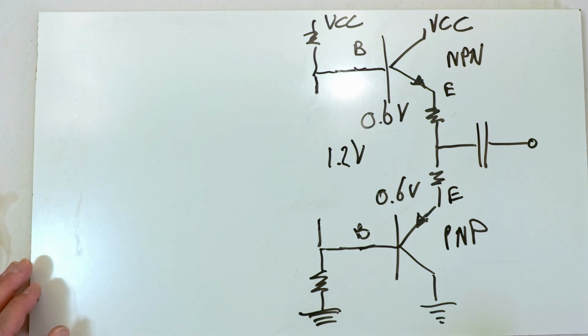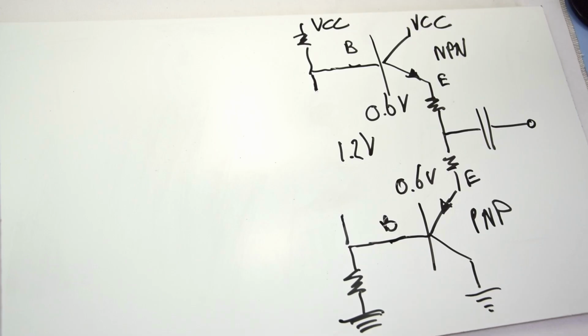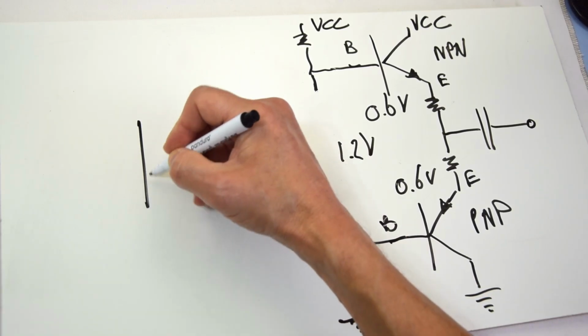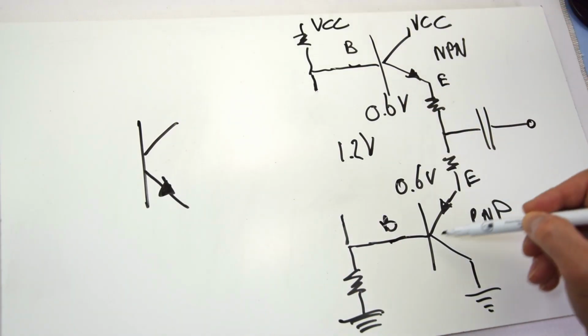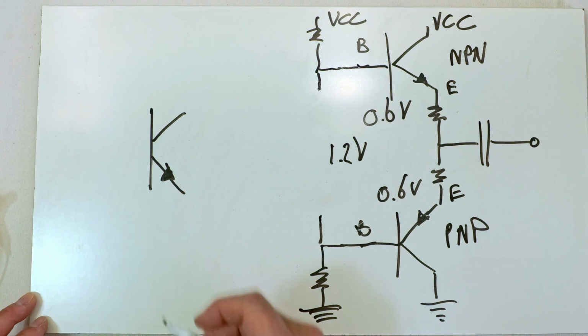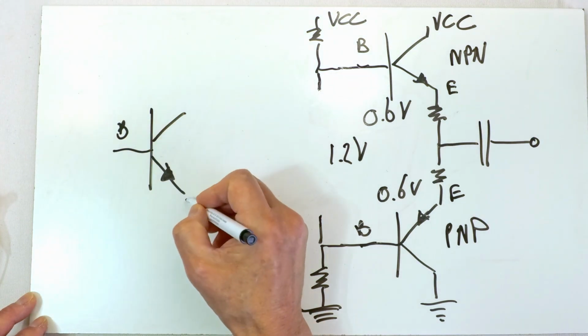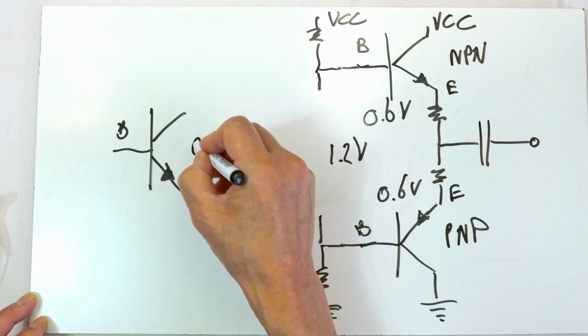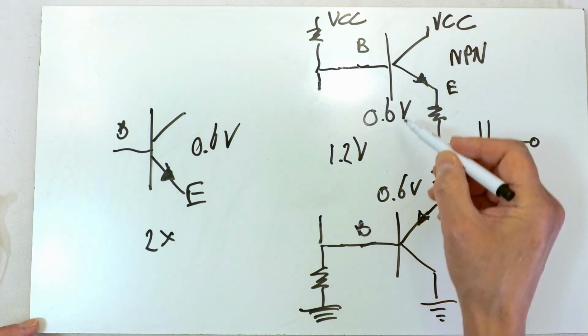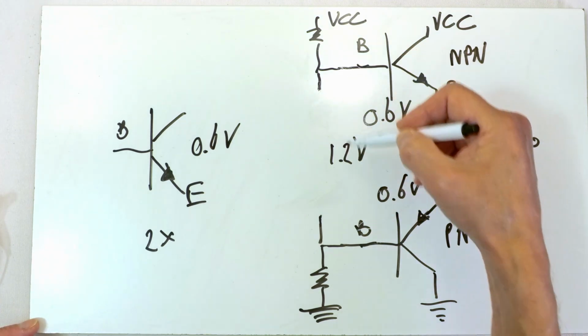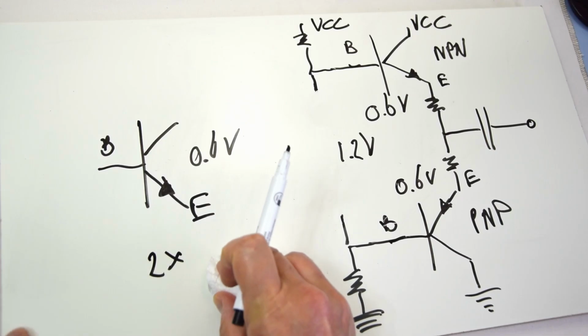The preferred way to deal with this crossover distortion is to use a circuit that's called a VBE multiplier. Let me show you what it does. The main element of this circuit is also a transistor, as it has the same characteristics as the transistors in this output stage. The voltage drop across this base emitter is also 0.6 volts. If we can multiply that by 2, we've got exactly the voltage drop we need between these two bases. So how do we achieve that?